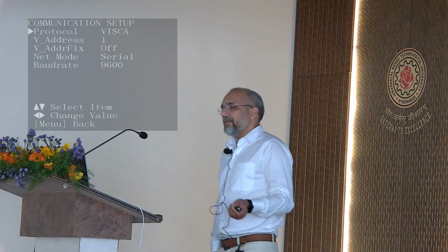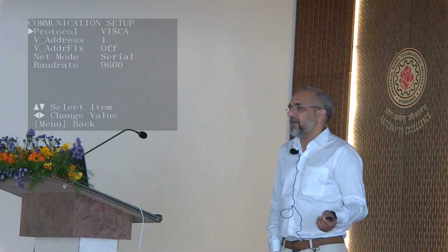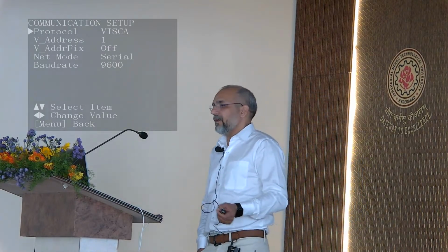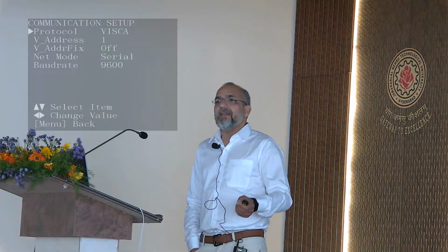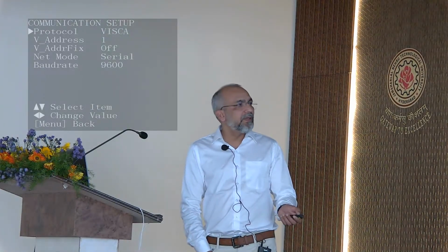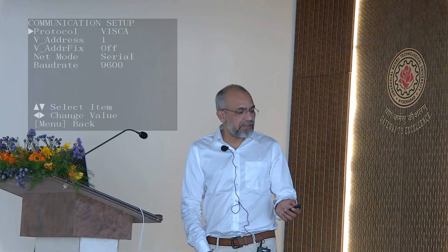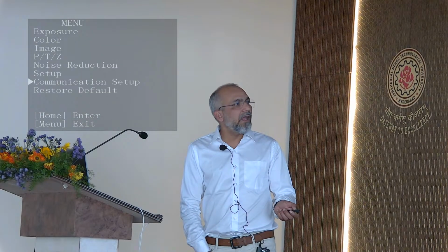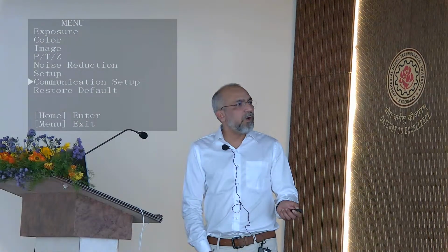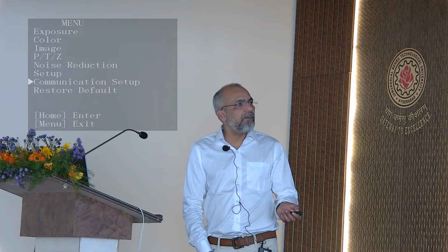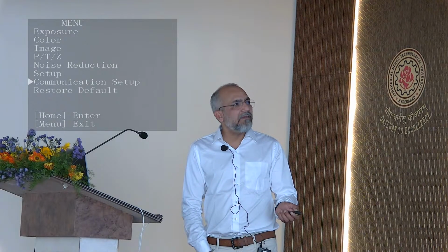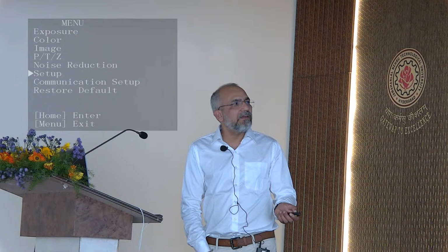And here is the process of how they have done it. First, you have the substrate. On the substrate, you deposit a gold thin film, and then you have the bulk material. For example, here you have MoS2, and then simply on the top you put a tape, and on the bottom you have this gold film, and finally you have a monolayer on the bottom.